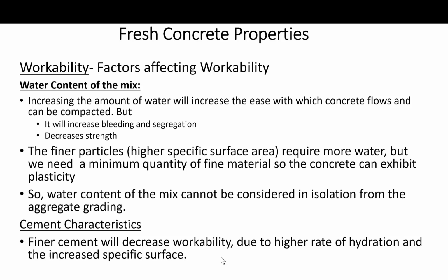First there must be enough water to absorb on the particle surfaces. Then water must fill the spaces between the particles, and this additional water lubricates the particles by separating them with a water film. Okay, and again, you're thinking the water has to do certain things before it becomes available for the workability of the mix.